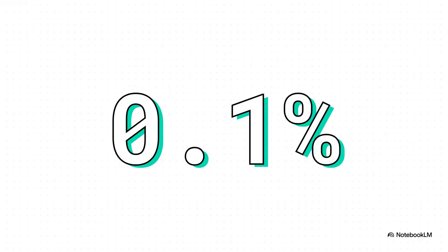But if you dig into the standard, there is actually a fascinating practical workaround. Because limits are based on that apportionment we talked about, sometimes the calculations hand you a limit so incredibly low that it's essentially just background measurement noise. According to the text, if your voltage emission limits at some harmonic orders drop below 0.1%, they can actually be capped at exactly that 0.1% threshold, unless, of course, there's a specific remote control frequency risk. This 0.1% floor is a game changer. It can absolutely save a project from completely impossible compliance targets.